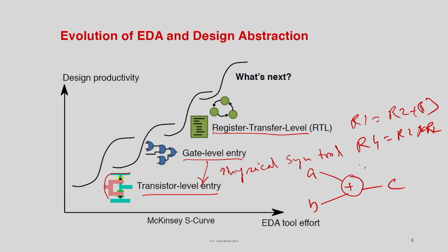So, this whole design complexity of the addition or multiplication operations is now getting abstracted out. So, at the RTL level I will get more reduction in the design complexity. It may be, say, from 1 billion to at least 10x smaller, if not more. We will get an advantage of at least 10x size reduction, so it may be around 10 million now.